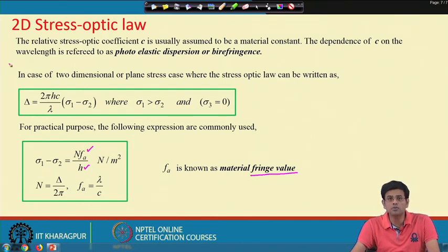Now, this can also be extended if you want to have a purely elastic material, for instance, which is not true always, because we see the viscoelastic behavior of photoelastic material. So, even if we assume, under a low stress state or the relatively elastic regime, purely elastic regime, a plane stress state, we can find out the strains with these laws, because let us see how we can find out the strains.